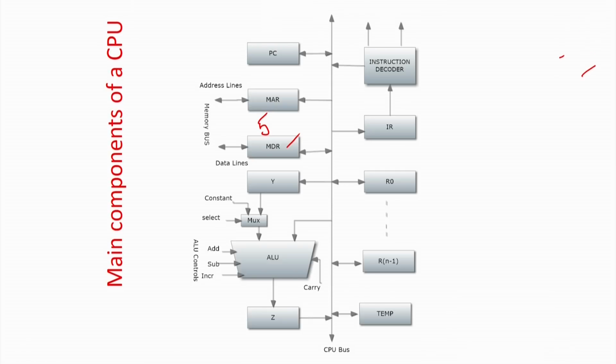So what people do is implement a bus structure, that is, a single wire or a single set of wires for different purposes, and whenever somebody has to use this wire, they have to use it on a mutually exclusive basis. Obviously simultaneous access cannot happen, but the cost is very reasonable. For example, the MDR is supplying data to R0; at the same time the ALU may not be able to use this bus to write to another register. It has to wait till the memory data register has transferred the value to R0, and only then can the ALU do it.